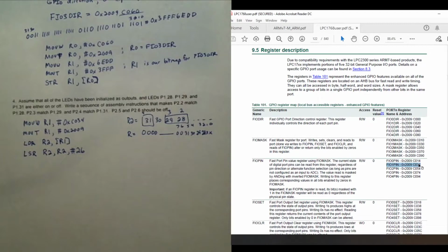That is where we want them to be so that LED 2 will match whatever value 28 had. LED 3 will match whatever value that 29 had. We have this problem just like in Lab 2 where the 30th and 31st bits are out of position because 30 doesn't have an LED and 31 does. So we need to try to move over 31 into 30's position.